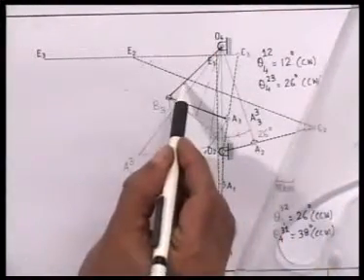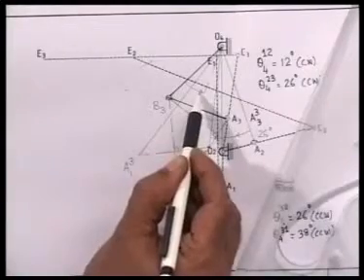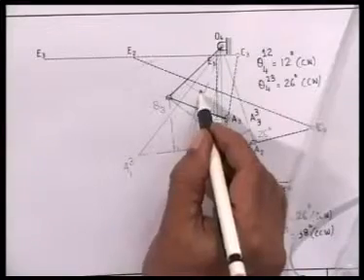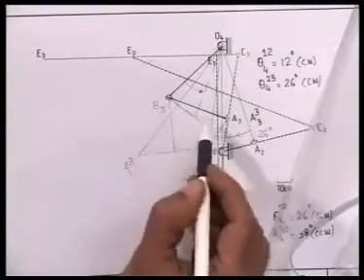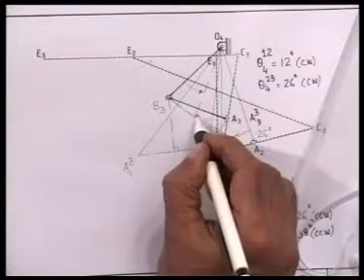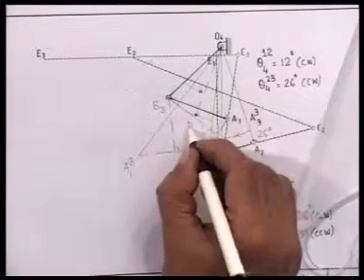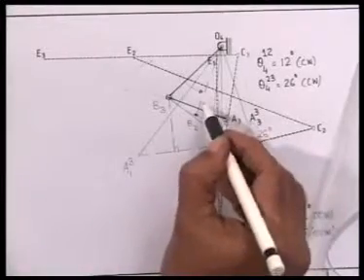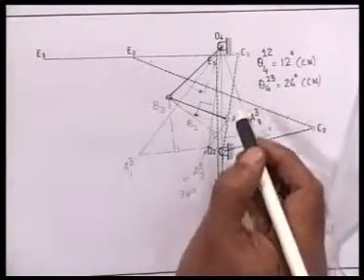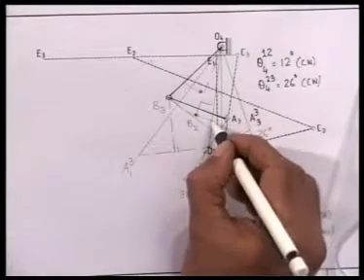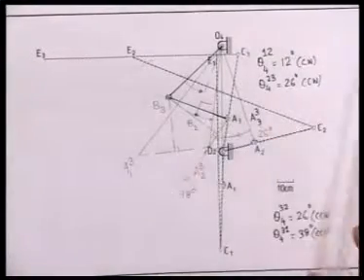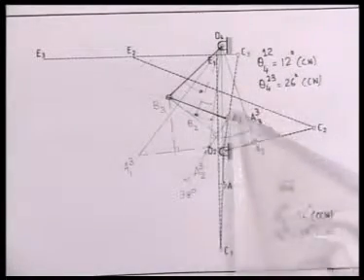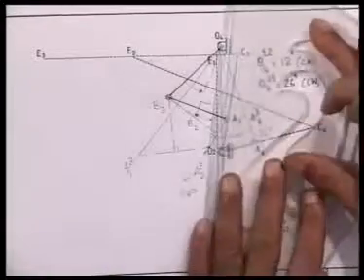This rotation is 26 degree in the counterclockwise direction, and B lies on this circle, so I can locate B2, and if I draw another line at 12 degree, I get B1, because from position 1 to 2 it is 12 degree clockwise, so from position 2 to position 1 it is 12 degree counterclockwise.